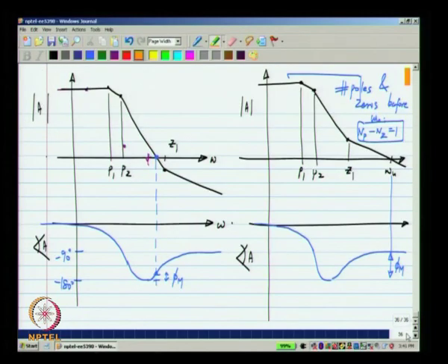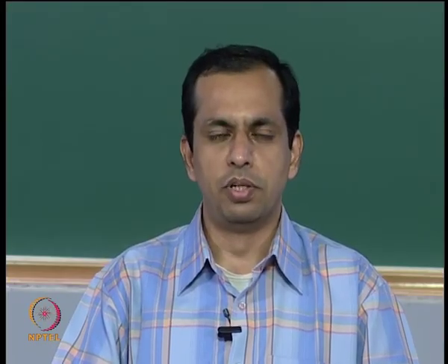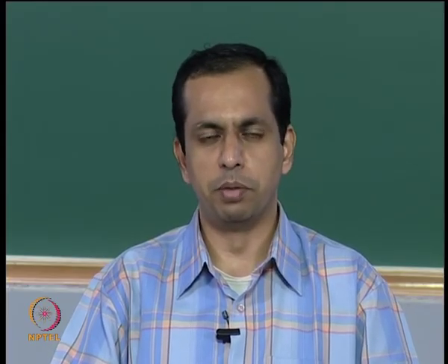Which in turn means that if you have NP poles before the unity gain frequency, you should have NP minus 1 zeros also, so that the phase shift comes back to somewhere between 90 and 180 degrees phase lag. This will become even more clear when we discuss the 3-stage feed forward op amp, but it is possible to have op amps with multiple poles before the unity loop gain frequency, but they also have to have zeros.